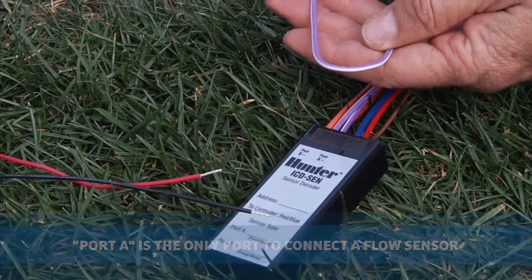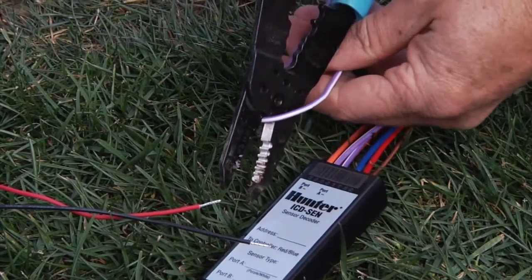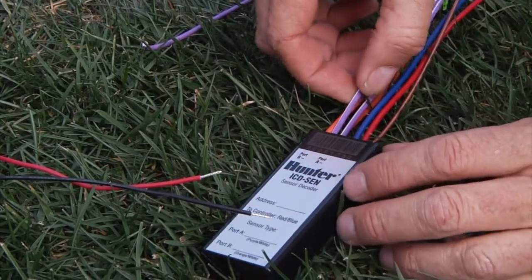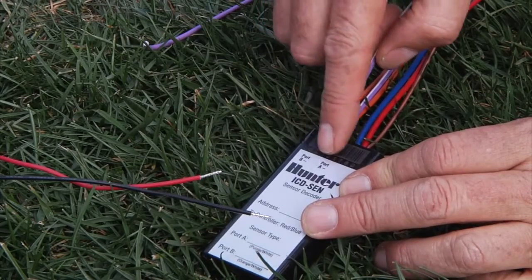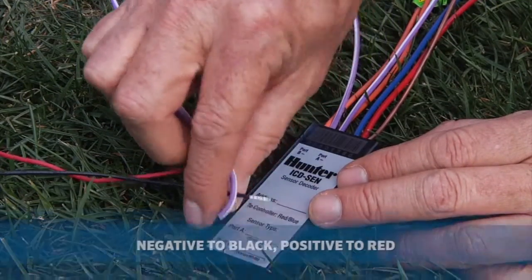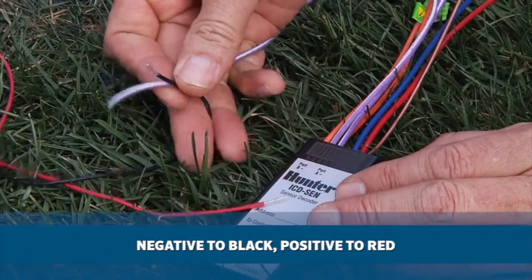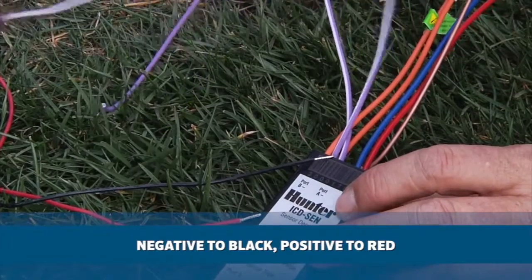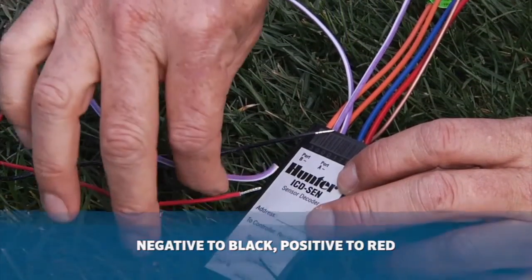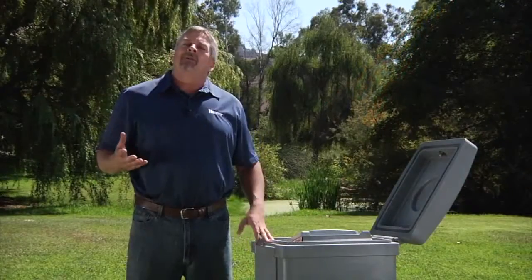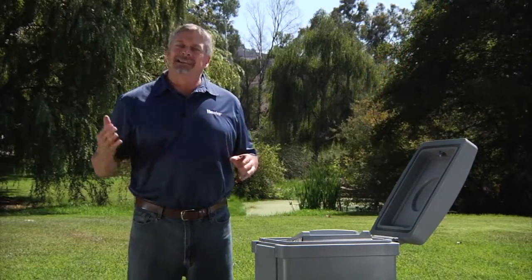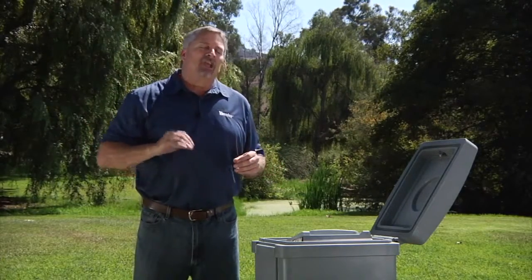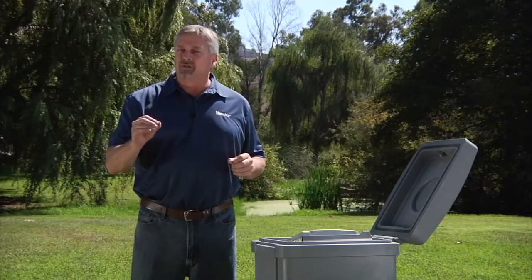When you connect a flow sensor through a sensor decoder, be sure to use the looped purple wires and that you observe polarity. As you can see, the negative side is on the front. Therefore, when you cut the looped wire, make sure to connect the black or negative wire coming from the flow sensor to the negative or front purple wire coming from the sensor decoder. Likewise, connect the red or positive wire from the sensor to the back or positive purple wire from the decoder. So remember, whether you're hooking up your Hunter FlowSync flow sensor directly to the controller or via a decoder through the 2-wire path, you only want to utilize 1 flow sensor per controller.